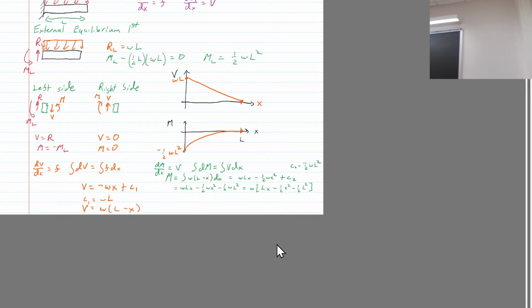So no bending stress. There is an internal bending moment, you're right, and that's going to be given by Py times A. But the bending stress is 0. So then it's going to be tau V minus tau T, at least for that stress.